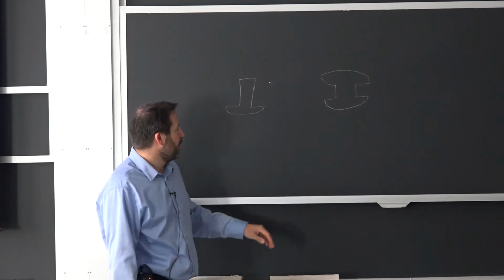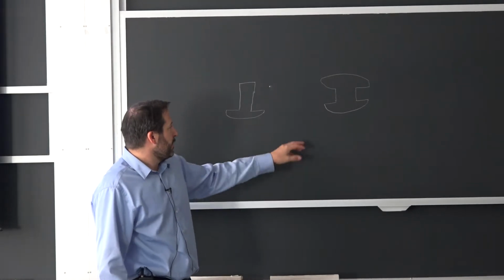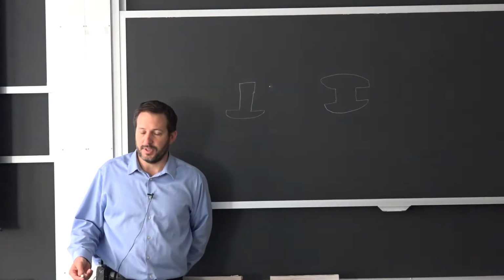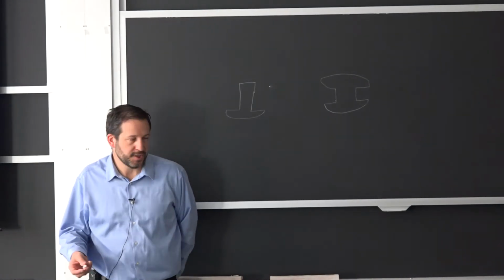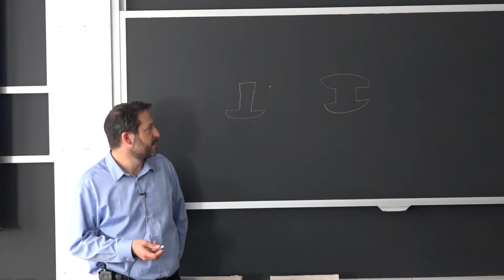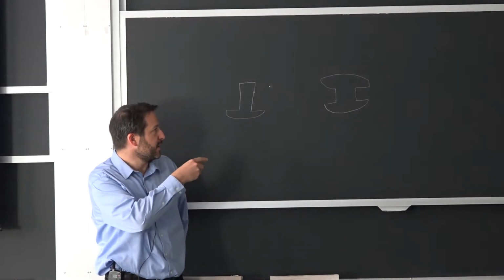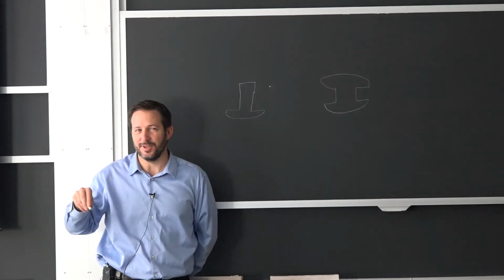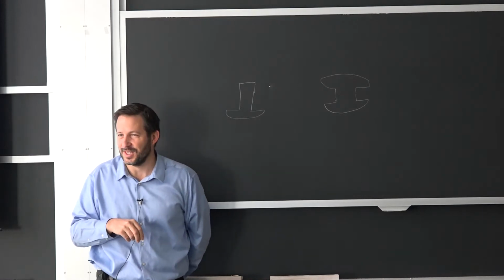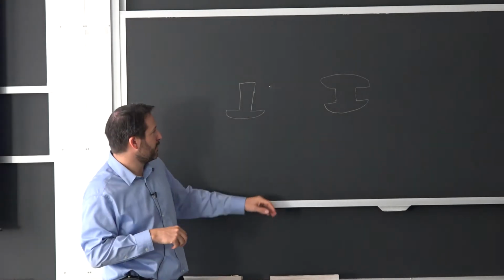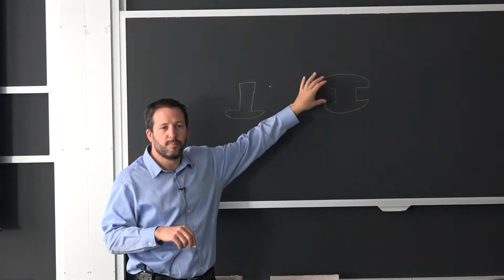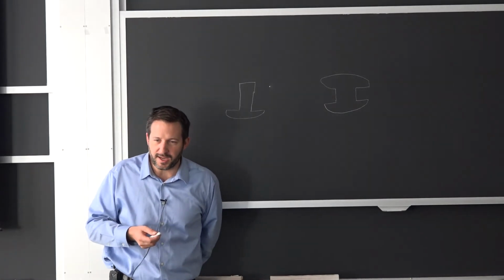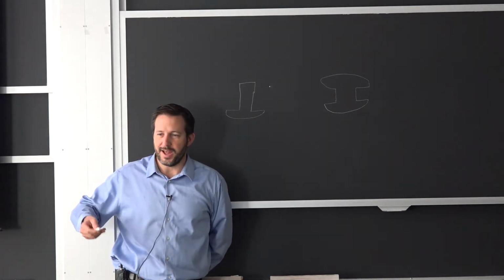There are a lot of parameters on this part that are going to influence the hardening behavior. It's not just the chemistry, it's the microstructure, and then it's how much you deform it. The only reason I know about this is I was actually doing the little hardness test to make sure from one week to the other that we were always getting the same effect on the rivet. And we would do complete destructive pull tests on a subset from each assembly. There was a tracking system where we knew which batch went where.